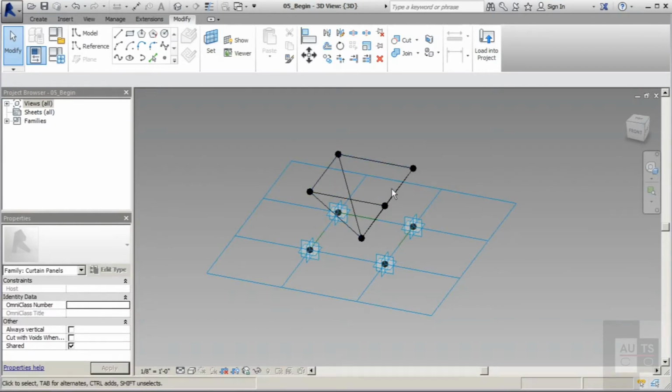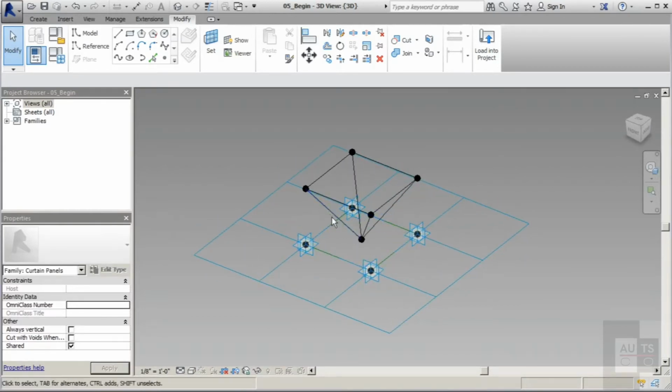So my strategy is I want these struts to be a little bit thicker than what's going on at these edges, because these are going to be holding in glass mostly, and these are going to be supporting the weight of the glass as well as anything else that might be on that roof, maybe some wind loads or maybe some snow loads, but maybe our site doesn't have snow. But either way, this is holding up the glass and the frame. It's pretty heavy, so I'm going to make this a little bit thicker.